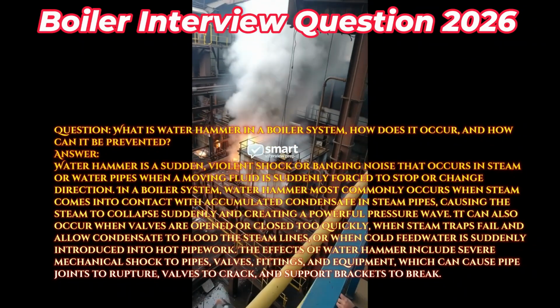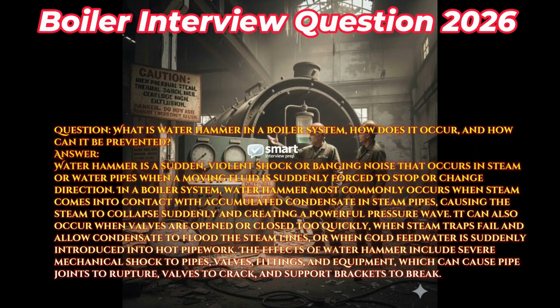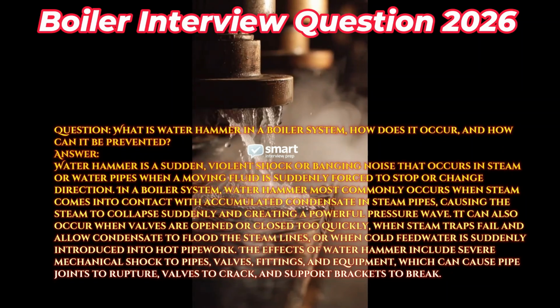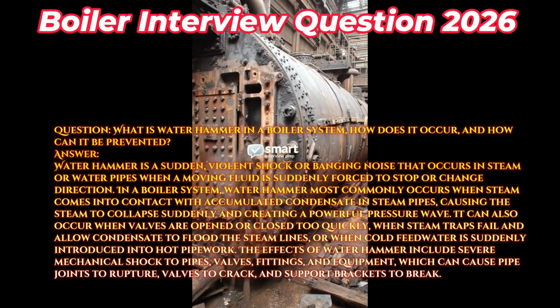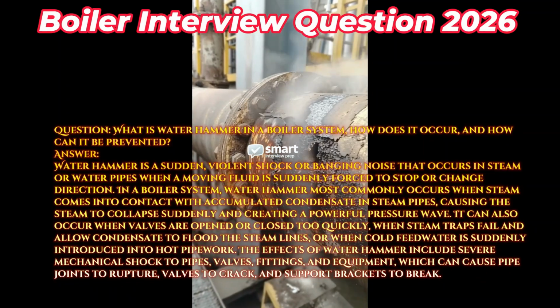It can also occur when valves are opened or closed too quickly, when steam traps fail and allow condensate to flood the steam lines, or when cold feed water is suddenly introduced into hot pipework. The effects of water hammer include severe mechanical shock to pipes, valves, fittings, and equipment, which can cause pipe joints to rupture, valves to crack, and support brackets to break.